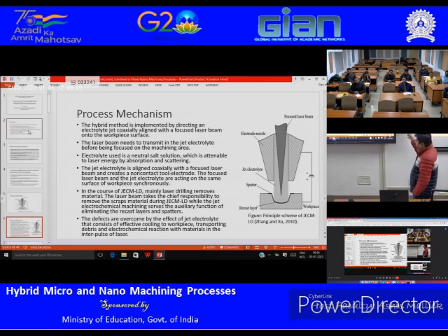And you know that in laser there could be some defects, but when you are using the electrochemical jet together, most of the defects are actually alleviated, and the jet itself can actually cool the part, because laser is removing material by thermal energy, so it will become hot, right? So the jet can actually cool the workpiece as well and reduce the defect.